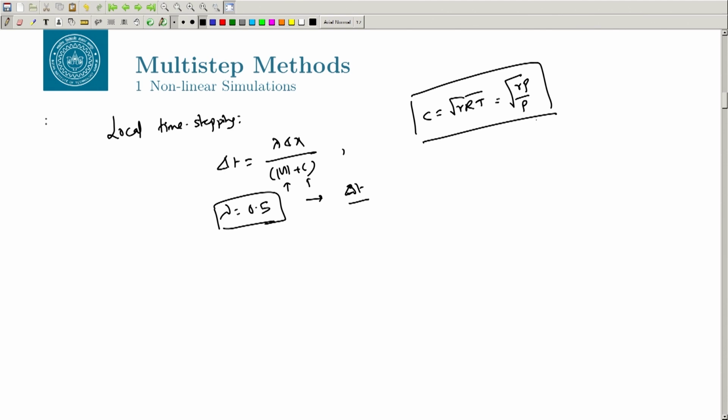To give an example, your time step will be delta t, the other time could be delta t plus delta t prime or delta t minus delta t prime, and so on and so forth. It will change in every time step. So, if you fix the CFL number, your delta t is changing, and in this kind of case the snapshots, or basically the results that you are getting at different times, are at unequal intervals.